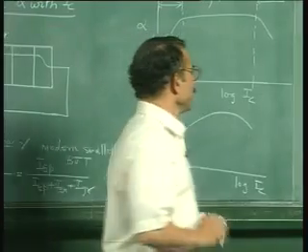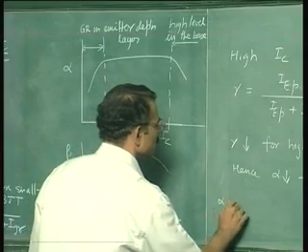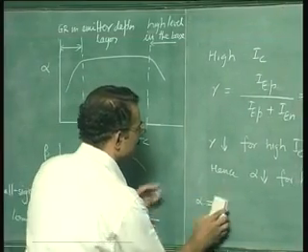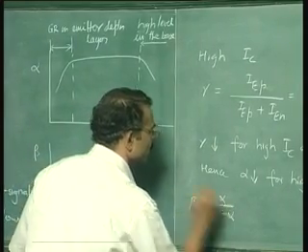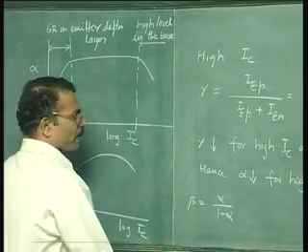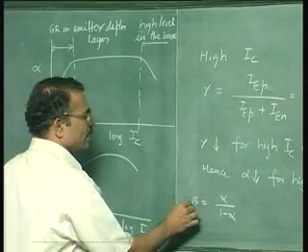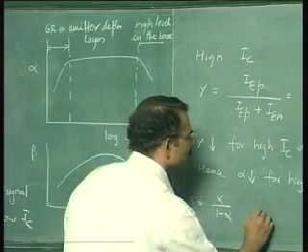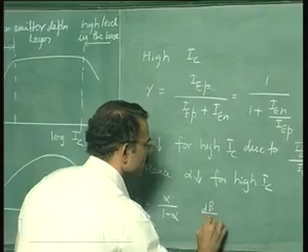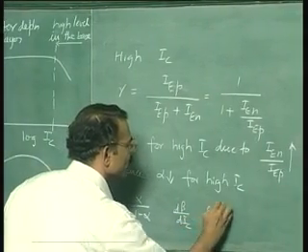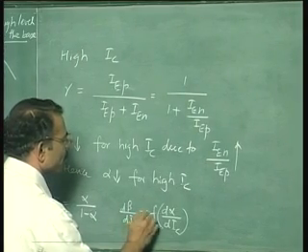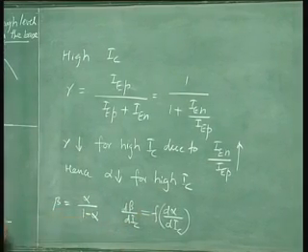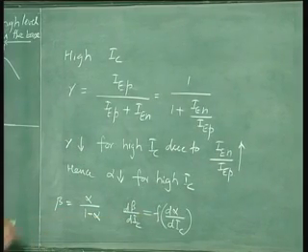You write the equation, beta is equal to alpha by 1 minus alpha, and then try to express d beta by dIC as a function of d alpha by dIC, just by differentiating, and you can very easily show that even for a small change in alpha there is a significant change in beta.